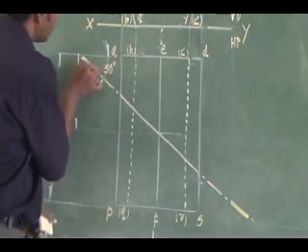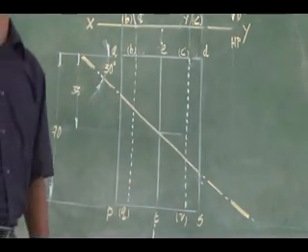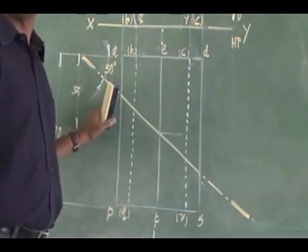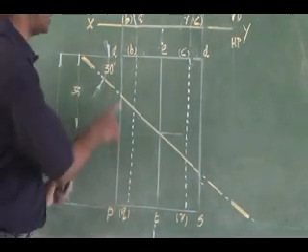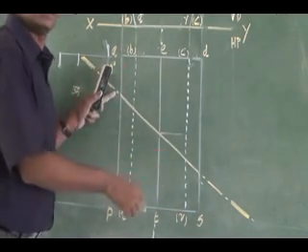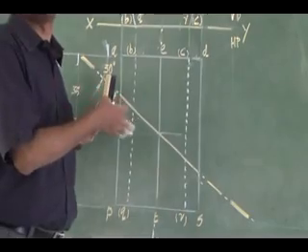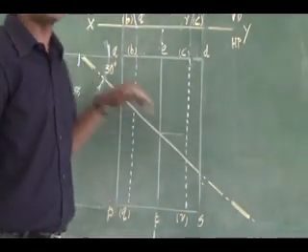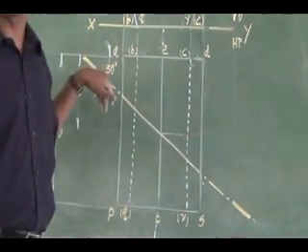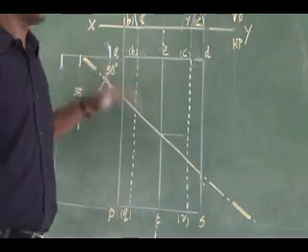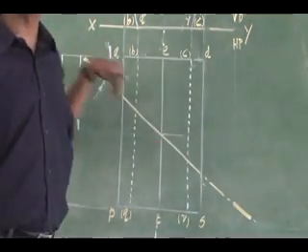Right. So this is the representation of the cutting plane. Then marking the cutting points from the left extreme corner, you mark the cutting point. Suppose this is a cutting point. How many side edges, not slant edges, does this cutting plane cut? It cuts all the 5 side edges.